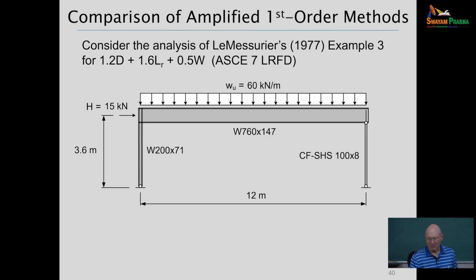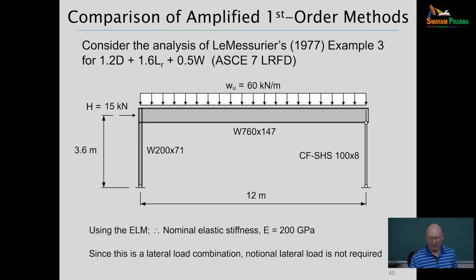Okay, all right, so now for the solutions we're going to do, I'm going to work the analysis according to the rules in AISC of what we call the effective length method of design, which basically means it's very similar in many regards to what you have in the Indian code, in my best understanding. You need to get a buckling load of the members to then get design strengths. So that's the effective length part, or buckling analysis based part.